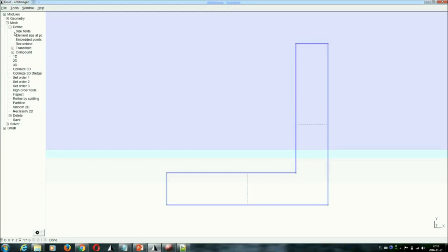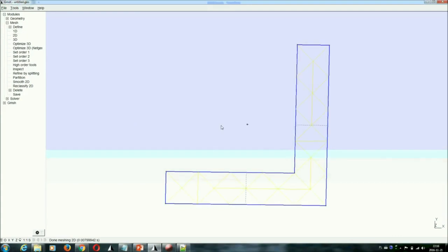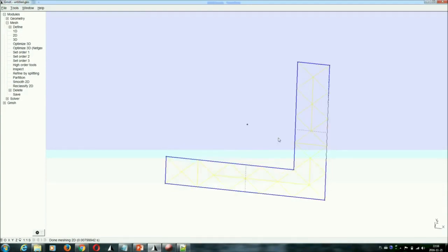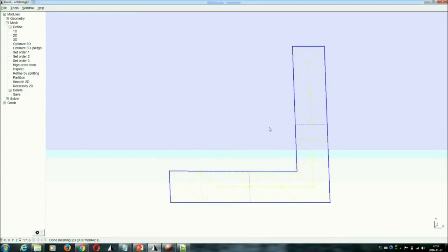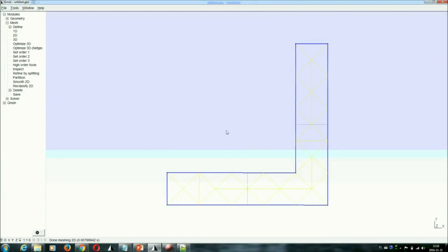In this first tutorial, we are not going to talk about mesh resolution and how to refine the mesh in a more advanced way. So we are going to focus on the simplest way of creating a mesh. This is really extremely simple. If you just open mesh, you click on 1D, then on 2D, and alright, in my case it is drawn with yellow, so you probably don't see much on the movie.